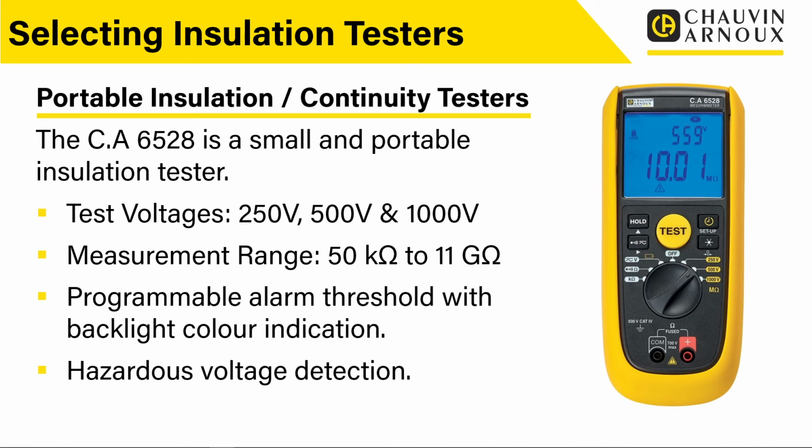You've also got the hazardous voltage detection built in. So if you connect this up to equipment and the circuit or equipment you've connected up to is still live, again, it will warn you of that and it won't let you actually carry out the test while that dangerous voltage is there. So again, that's a great safety feature built into this.